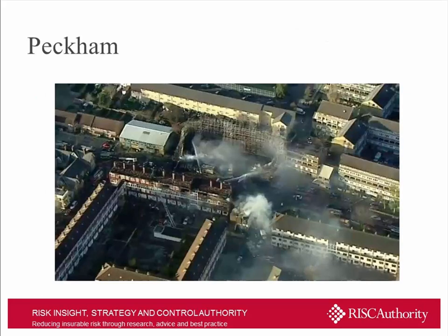An example there of a fire that I think we're probably all familiar with, building during construction, Sumner Road in Peckham, a single building, 4-storey timber frame block with a flat roof. Non-flame retardant timber was used, and the frame itself was unprotected to all intents and purposes. It had a weatherproof breather membrane installed. 10 people were admitted to hospital as a result of the fire. And the fire occurred 12 hours after the last member of staff had left.